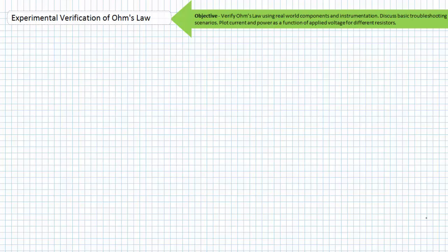Let's introduce some basic errors in our circuit. There's only one element, so the troubleshooting opportunities are pretty limited. But you'd be surprised how often these scenarios occur in early labs. We'll introduce open circuits, short circuits, and other scenarios induced by incorrect placement of components, wires, and instrumentation. Opens. Like I've previously said, the open circuit is the troubleshooting scenario you'll most likely encounter,